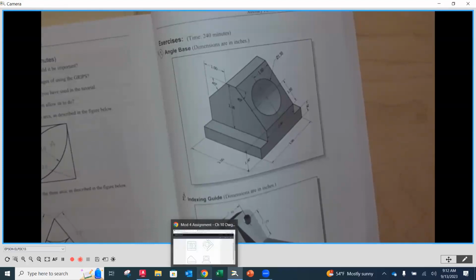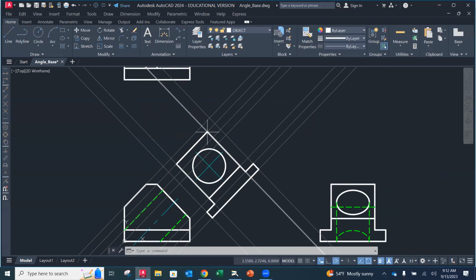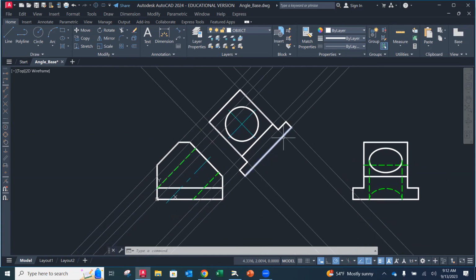Oh, yeah, let's look. These guys here. So what I did was I created a construction line through this point and that point on your rectangle. And then I did an offset just of the construction line. Does that make sense? 0.5, because that's the width of those little flares, right? So this still is going to be 3 inches wide in this view. Okay, this is that depth dimension, if you would. Okay. So this is 3 inches in the right side view. This is still 3 inches right here.